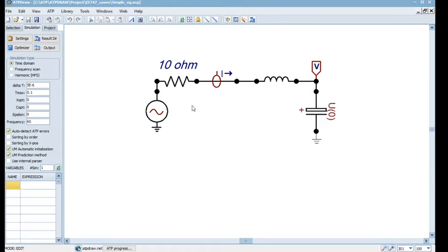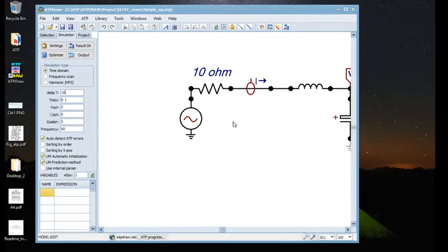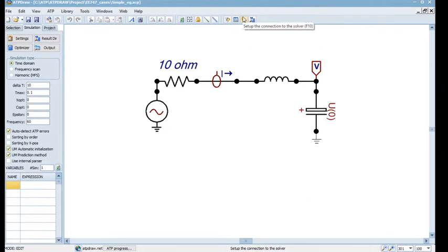So we assume you have done this much, and now let's go to the settings part. To begin with, delta t is the step size. Let's begin with something like 10 microsecond order, because dynamics we are already comfortable with. These are LCs. L is 63.3 millihenry, and capacitor is 10 microfarad. It's a very common example we have seen most of the time. It has a resonant mode of around 200 hertz, so 10 microseconds should be more than enough, in fact, fine.